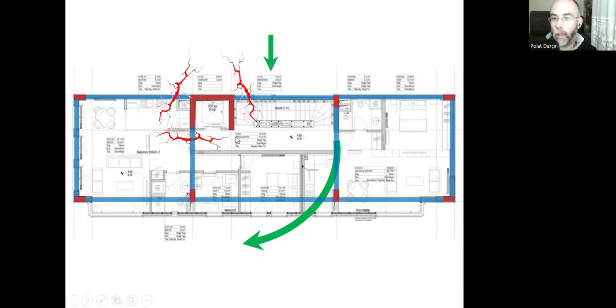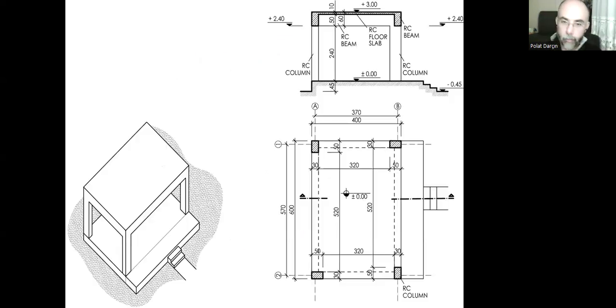But when we do the shear walls, if you create a heavier part for this building and cause an imbalance, we can solve that problem by creating larger columns or even shear walls in other corners so that we can have an equally distributed load throughout the building, so that again, with the lateral force, the building will sway normally without this rotation.